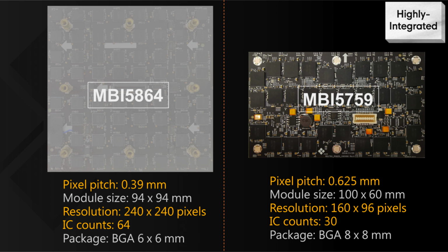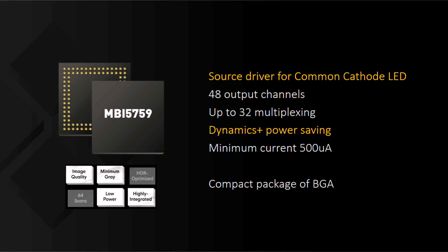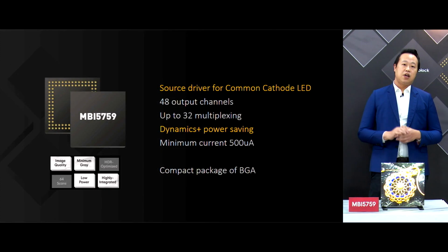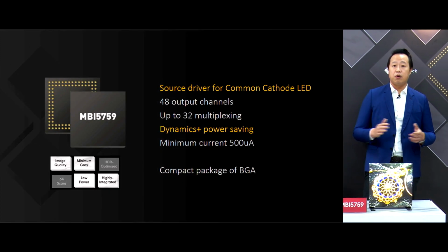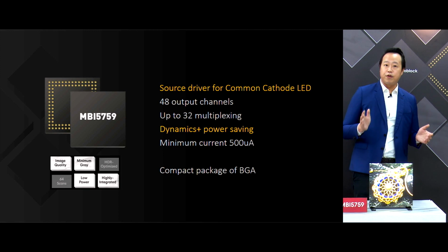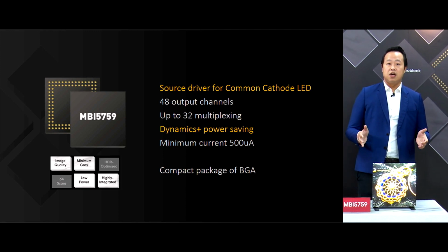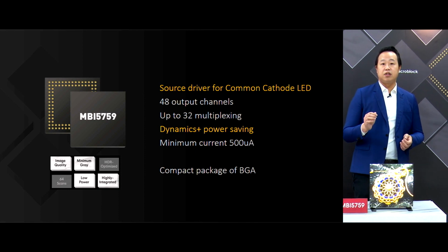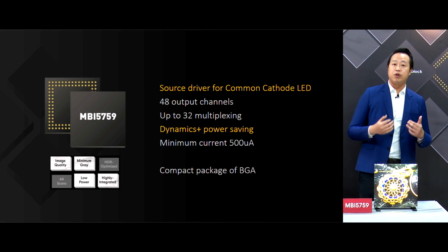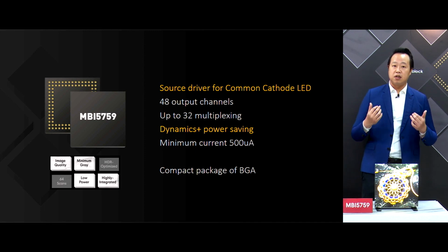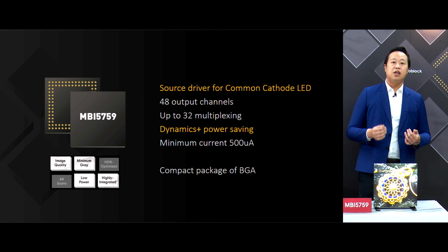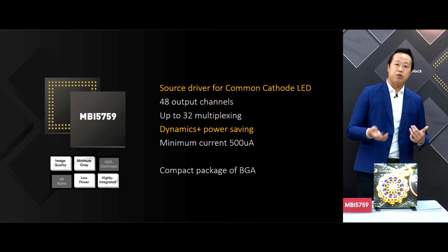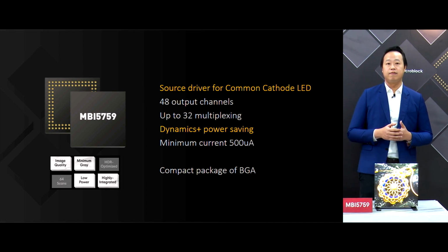So now I will wrap it up about these two latest drivers. For MBI 5759, like what I just mentioned, it covers 4 elements in new basics, especially highly integrated and also the low power. That is because it's able to support the common cathode LED technology. And if you enable the dynamic plus power saving, you can save more power no matter any time when you operate your LED display system.